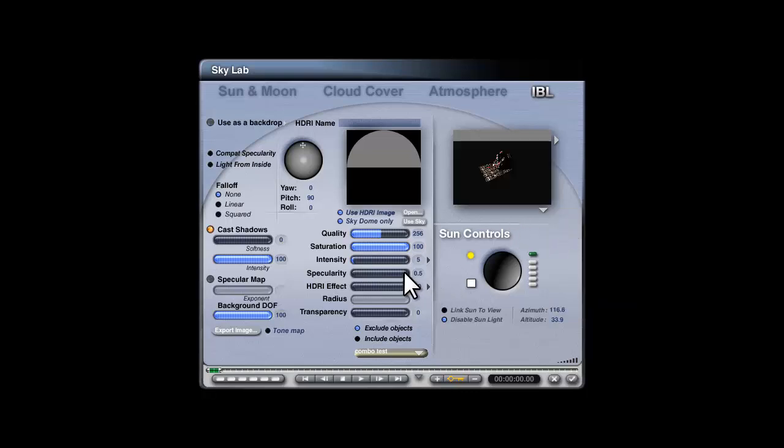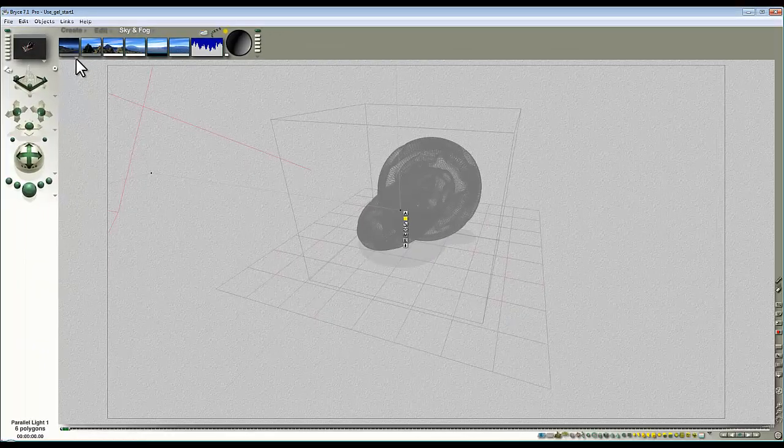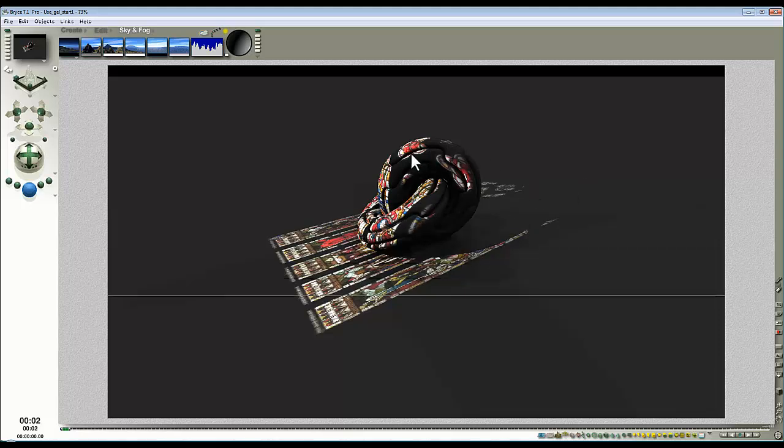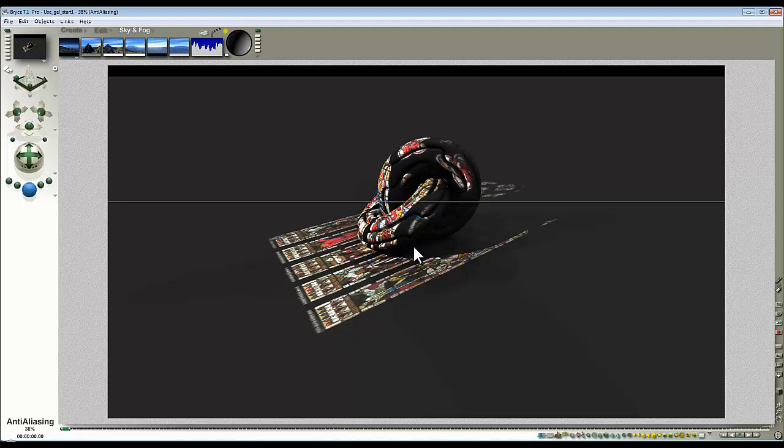Do a render in scene, and then set the quality down and just provide a bit of general lighting from this of an appropriate low level. So let's say 25, right, maybe 35. Okay, and then if I check out of here now, I'll just set my sky to fully black again. We can have an integration between the light source and some general lighting to provide a bit of information in that shadow area, for example.